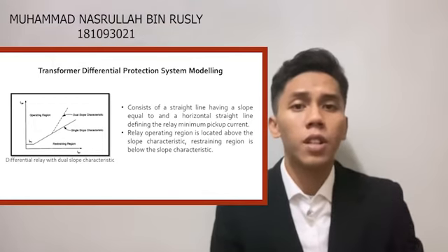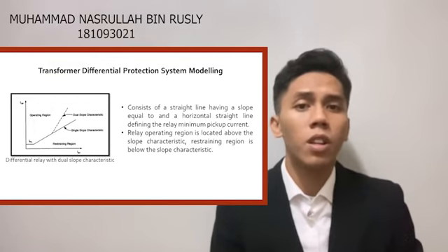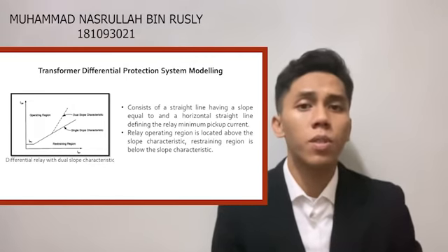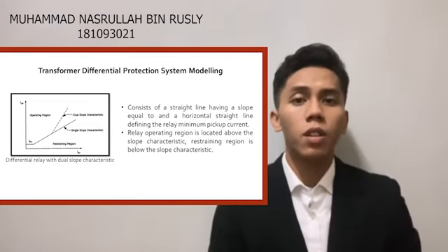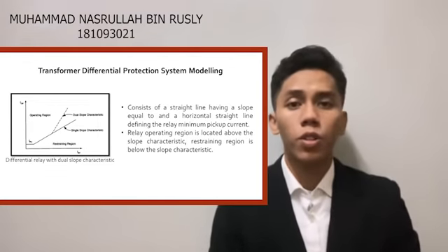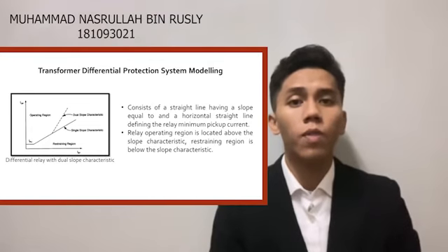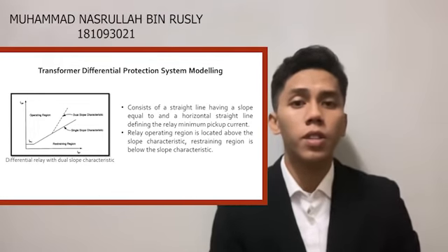A variable percentage or dual slope characteristic, originally proposed by Sharp and Glassburn, further increases relay security for heavy current transformer saturation. It is shown in this characteristic as a dotted line. Current transformer saturation is only one of the causes of false operating current in differential relays.